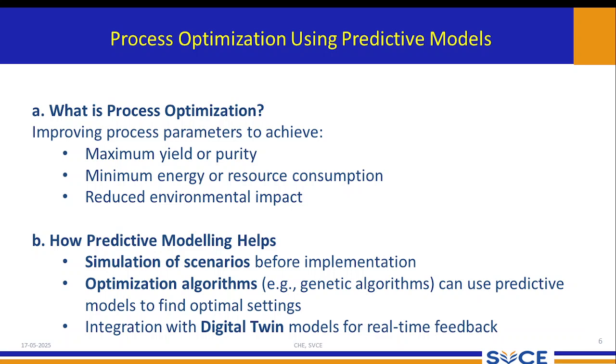So what are the things I need to do? Either I need to find and vary the glass transition temperature, or else I need to reduce the amount of additives added in the extractive solution. Okay, so this is how this control works. When you apply model predictive control, we can put a controller on the inlet of the feed which is coming to the spray dryer.